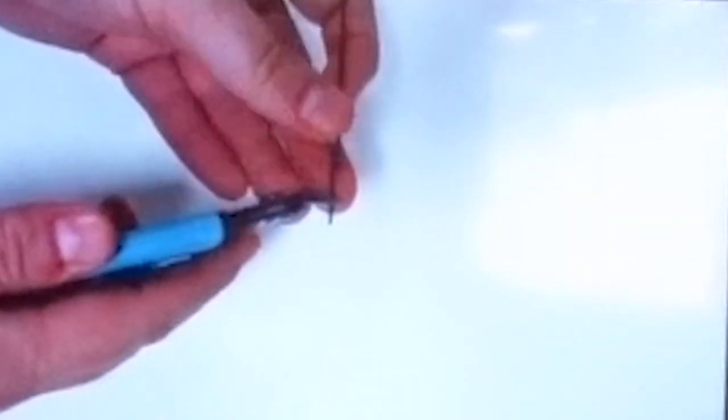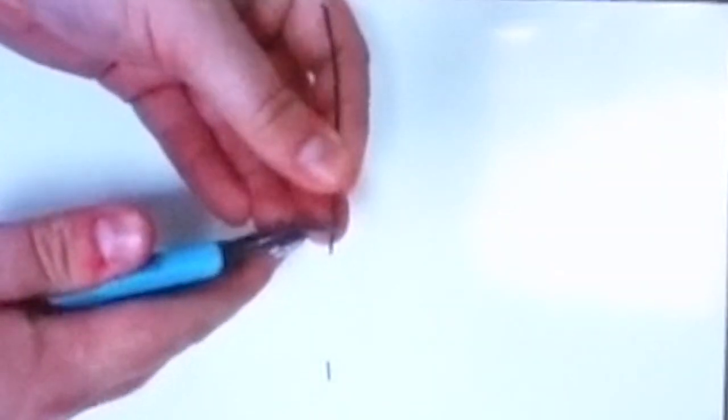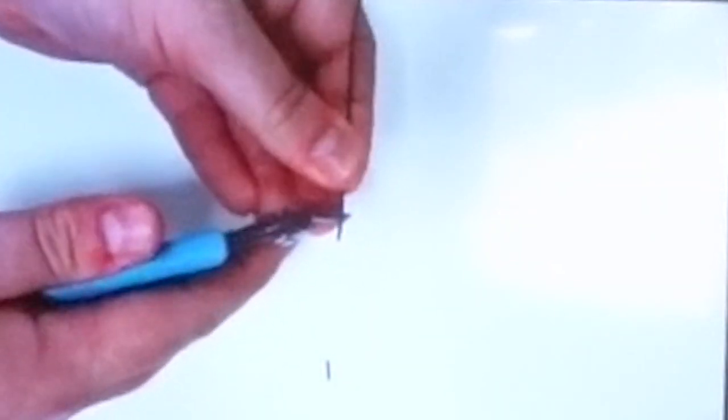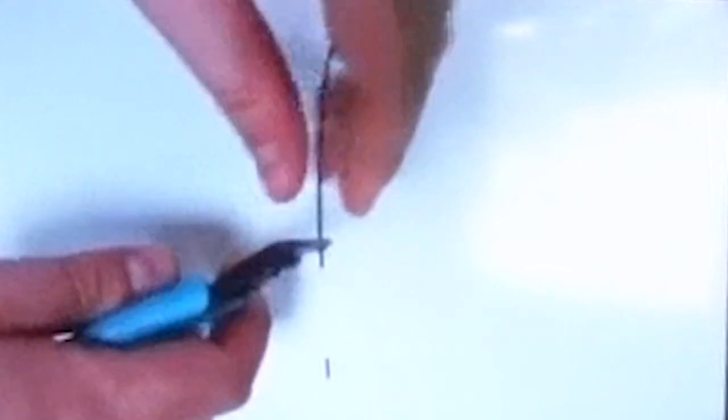So we've got our bit of wire. Obviously, we can't plug this in because we don't have the actual conductor exposed on the ends. It's still got the insulation. So we can grab our flush cutters and size up about how much we want and then just gently squeeze. If you squeeze too hard, you'll just cut the end off like that. So you want to gently squeeze, and then I will rotate the wire around.